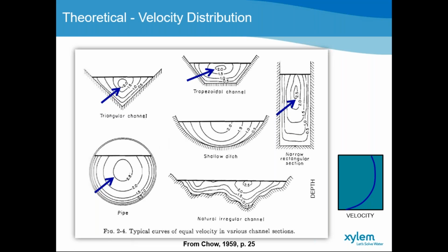If the channel or section is broad and there is rapid and shallow flow present, or the channel has smooth sides, the maximum velocity would occur at the surface, such as in a shallow ditch and natural channel. Banks do not have any impact on the central velocity region if the width is greater than 5 to 10 times the depth of the flow, depending on the surface roughness.